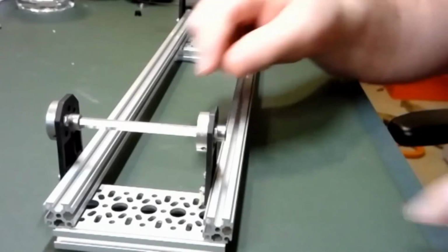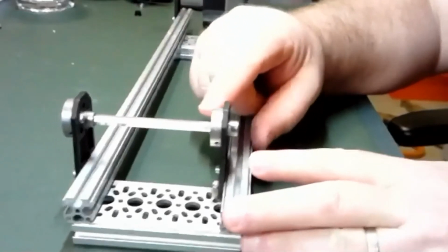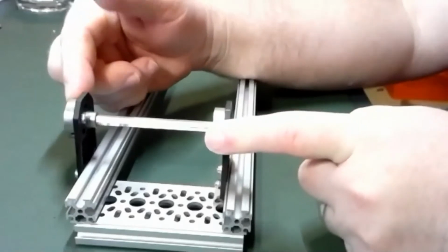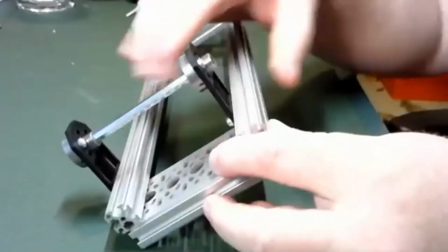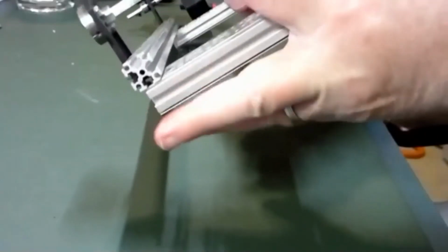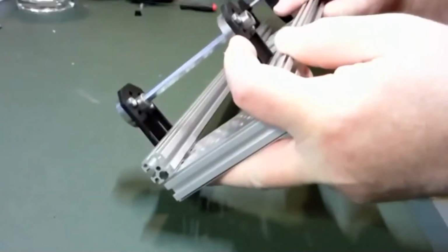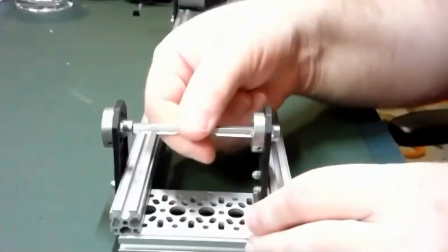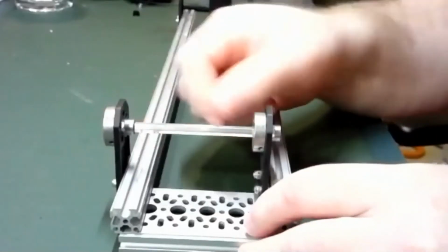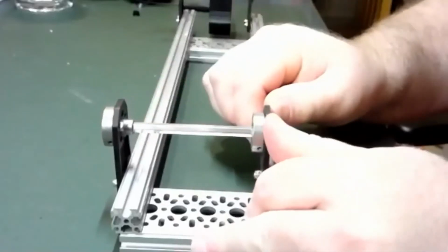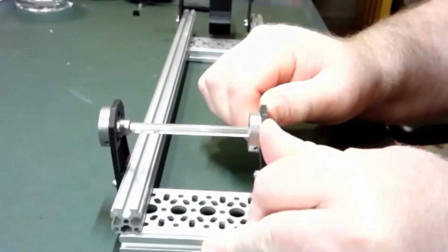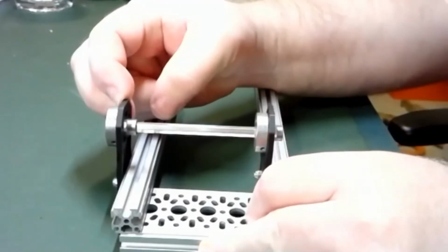Now the axle is attached to these motion hubs that REV has come out with within the last year. The motion hubs can attach to the motion brackets, and they have a set screw so that they're attached to the axle, so the axle doesn't move at all. You don't need a collar because the hubs act like a collar. Once that's in place, this thing is structurally very strong. I'm really pushing on it and you can see it barely bends at all.